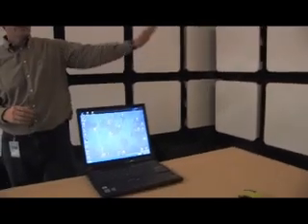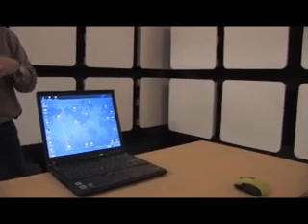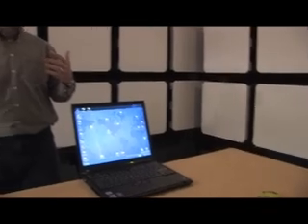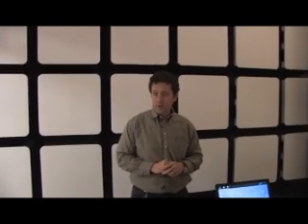You see all these materials on the wall. These are absorbing materials. So they absorb RF energy and keep it from bouncing all around. And ideally, we could do this in an open area test site with no walls, away from any noise sources, and that would give great results. But where we are, we have the shielding to create a quiet level, and then the absorbing materials sort of negate the shield, so they sort of cancel each other out to some extent.